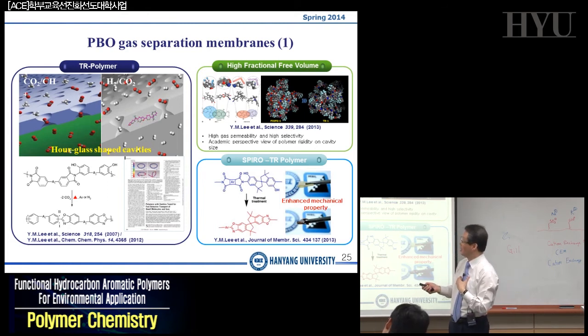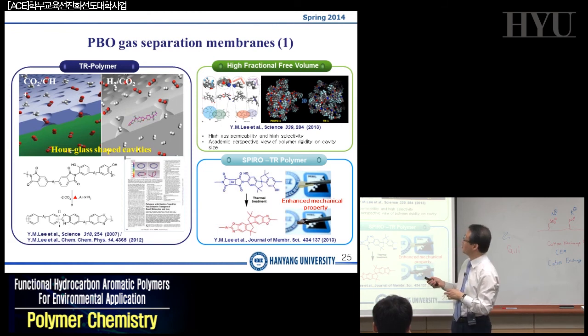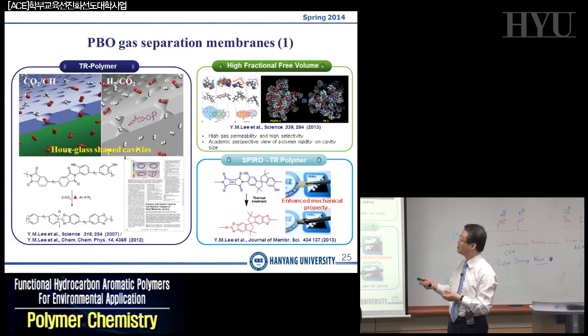And that's what we have done. In this case, the polymer was made from polyimide to polybenzoxazole, and therefore we have about several hundred times larger flux only for CO2, and also for oxygen from the air, and hydrogen from CO2, and so on, depending upon the chemistry, and we have been very successful in separating those molecules.